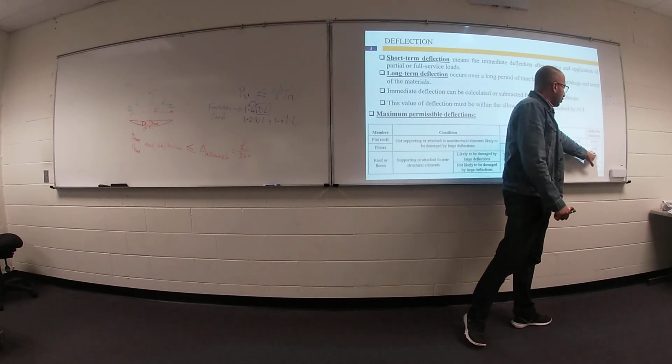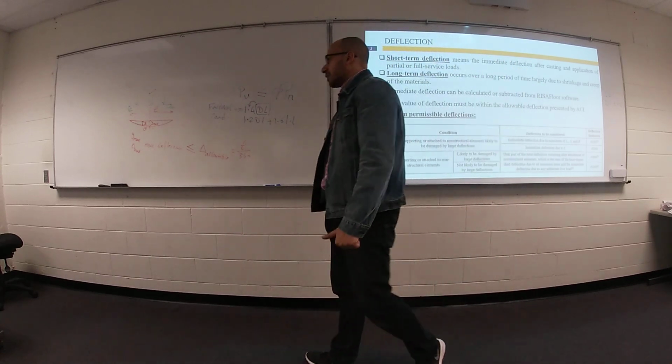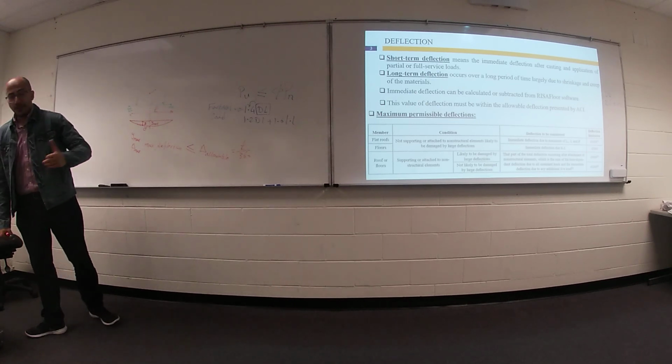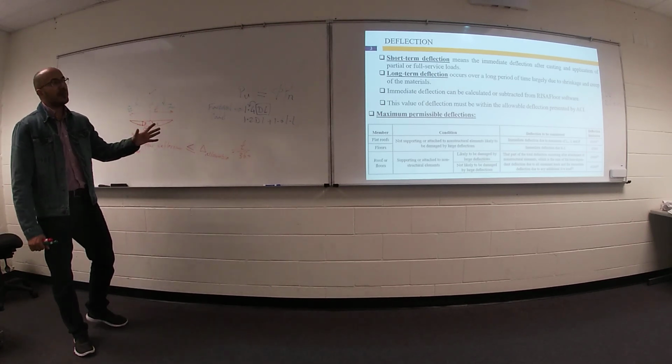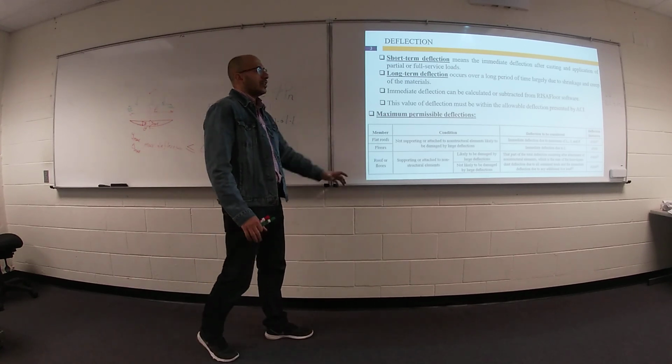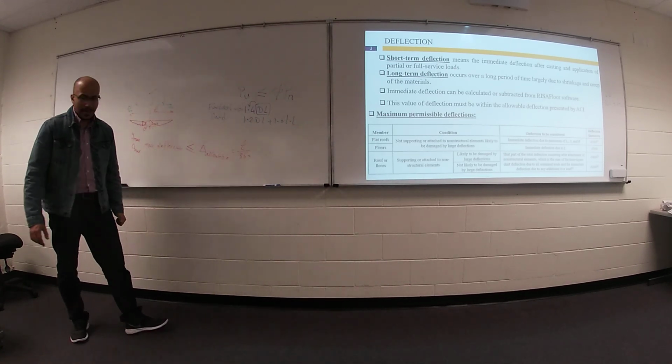So after you are done with your design, your steel reinforcement is okay, your stirrups are okay against shear, nothing related to your torsion, everything is good. You did your design. Please go ahead and check your deflection. Your deflection must be within the allowable.